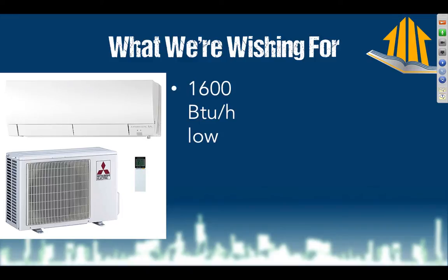And that's because we're dialing in everything just like we've talked about for the last 3 webinars here, and we'll do on the last one next week. This thing will go down to, on the low side, 1600 BTUs per hour of heat or cool, and that's good because that's also in my range. And to run either of those in cooling or heating, it only takes up on the low side 110 watts. That's much better than my 460 watt window air conditioner. That's super efficient, and I like that. So we're going to try to do this, especially because